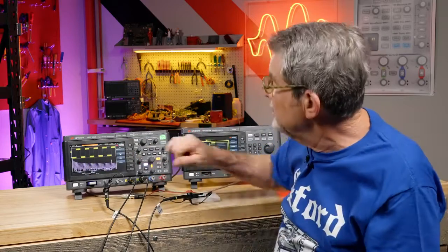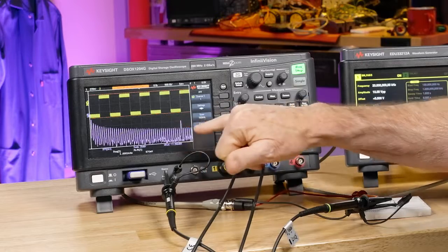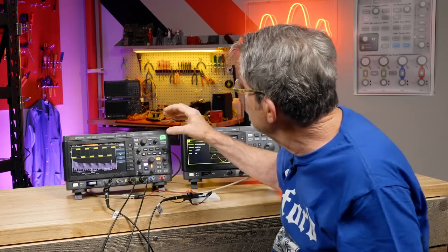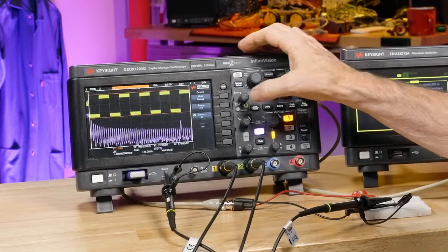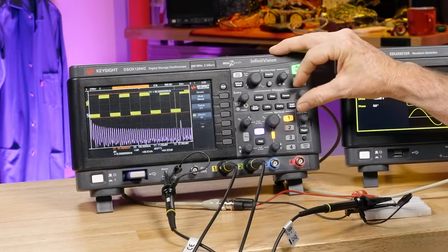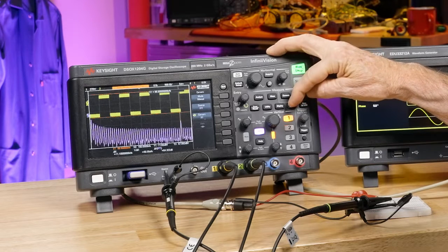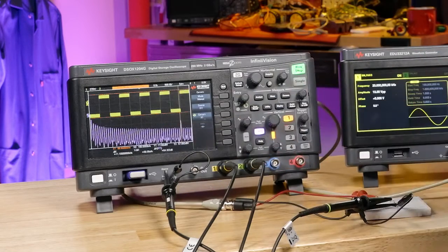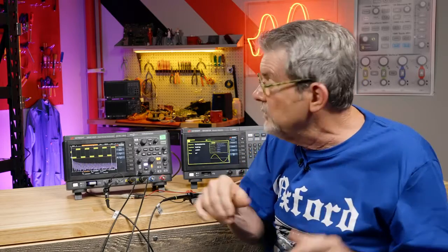But there's an oddball, this one out here. It's sticking way up. It's not continually decreasing in amplitude. That is a component of coupling. Now let's measure it. I'll turn the cursors on, and let's just measure the frequency. I'll put it out here, and it measures about 89 kilohertz. There's an 89 kilohertz sine wave coupling on to this 1 kilohertz square wave, and FFT popped it out right away.